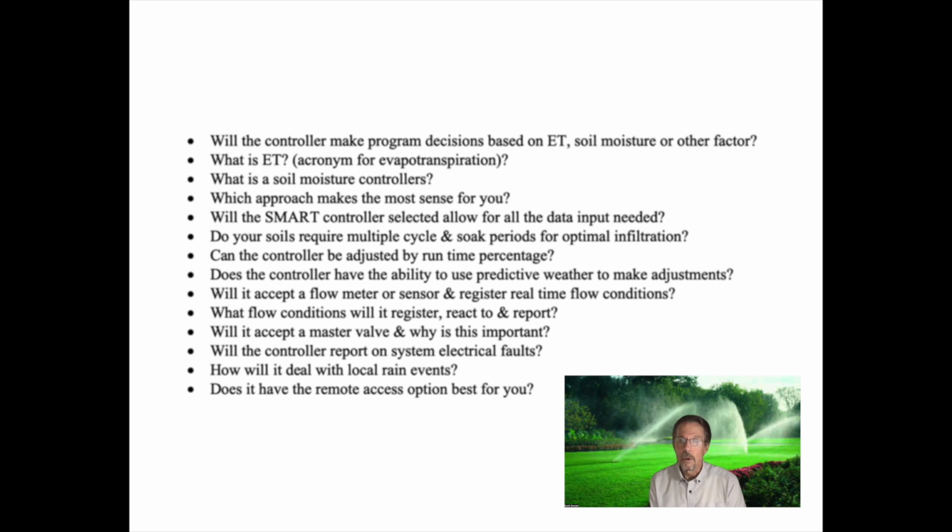Many controllers on the market today provide and utilize accurate ET data to make program decisions. What are soil moisture controllers? Soil moisture-based controllers rely on a soil moisture sensor or multiple sensors to make program decisions based on actual soil moisture levels. Which approach makes the most sense for you? Either can work when set up properly. It really depends on the size and complexity of your project. Ask for a specific explanation of why either is being recommended for your site.